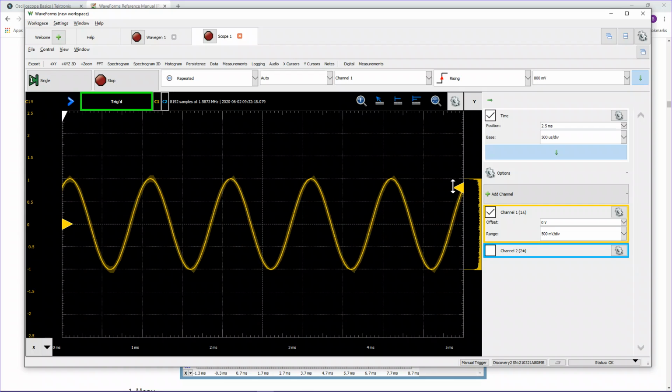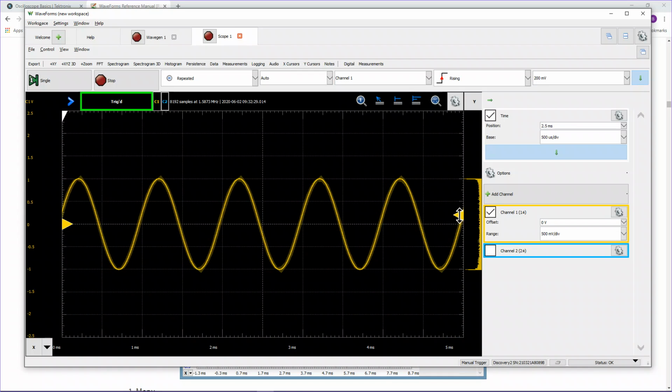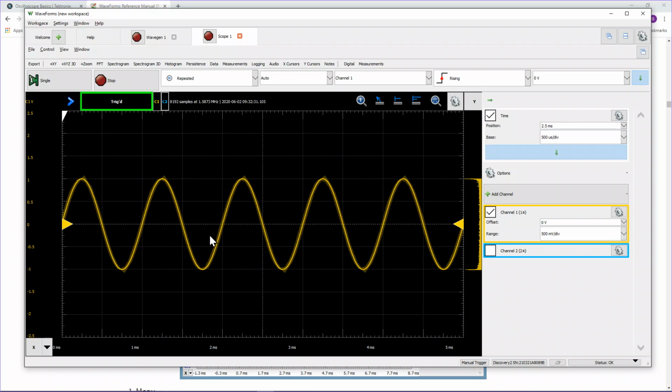So if I move it up right here, you'll notice this point of the arrow comes right over here to this level of the signal, and if I move it down while you're watching that, you can see that the starting point is changing to adjust the voltage on this waveform to the exact point that this starts, and that's called triggering. And there's a lot of settings for that.